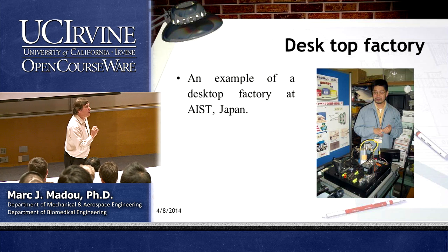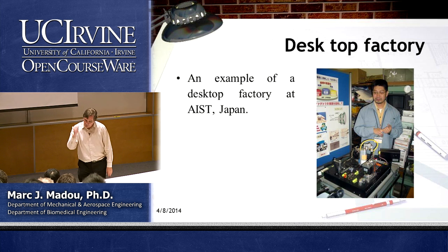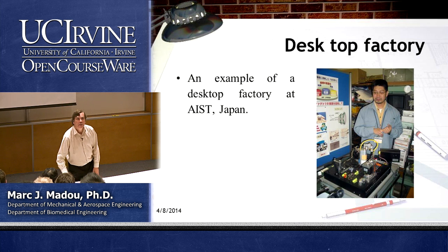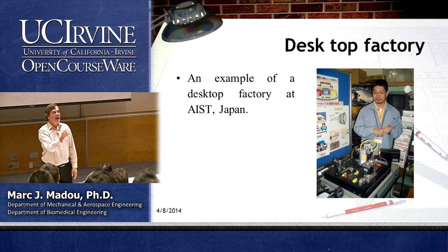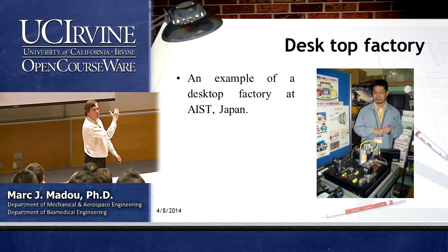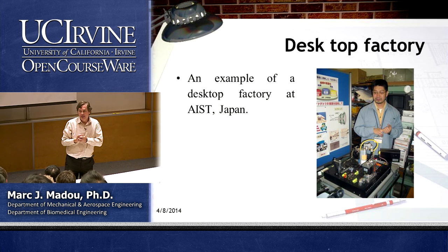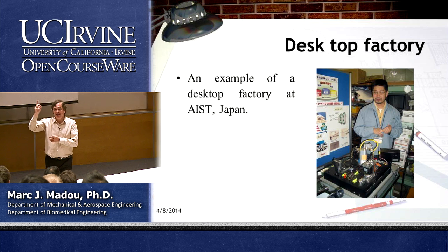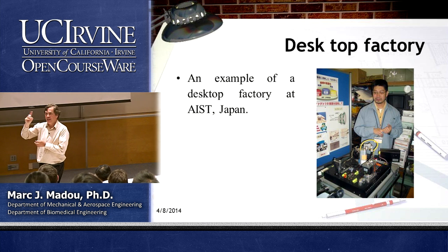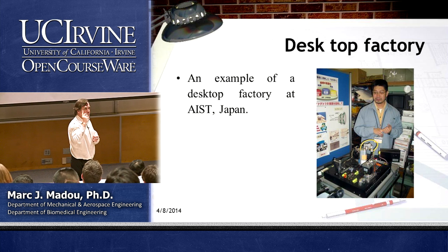With ultrasonic machining, we will be blasting hard particles onto a substrate to machine a structure. And with focused ion beam milling, we will create a plasma, extract ions, and bombard the workpiece with ions. So we will actually be machining with an ion. And actually today, focused ion beam milling is the most precise mechanical machining method available. Better than electron beam machining.